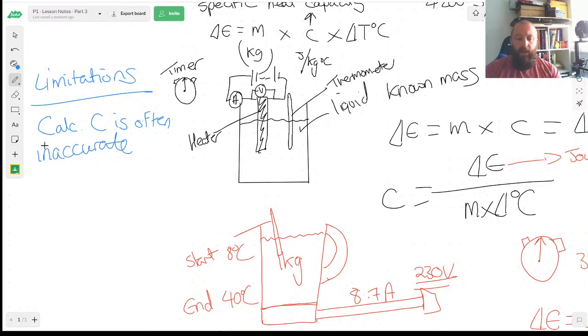Okay? So what we should do in an ideal world is we should insulate it. Because if we can insulate around it, and we can talk about the conduction, the convection, the radiation. So realistically, if we want to go properly overkill on this, we would want this whole system completely sealed with a vacuum, with some insulation material, with a shiny surface.